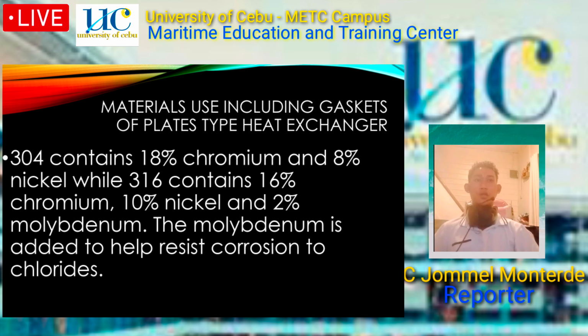Plate and gasket materials: plates for PHE can be obtained in all pressable materials. The most common materials are stainless steel 304 and stainless steel 316. Gaskets are available in a wide range of elastomers, such as nitrile rubber, also known as nitrile butadiene rubber or NBR. This rubber is unusual in being resistant to oil, fuel, and other chemicals.